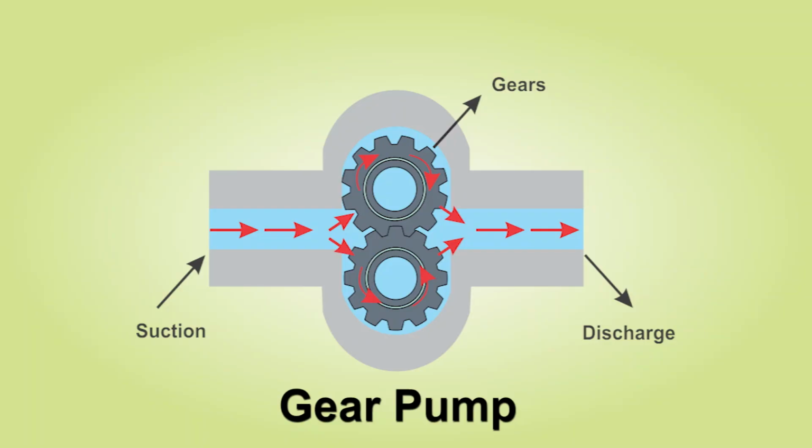Gear pump. Gear pump uses the action of rotating cogs or gears to transfer fluids. The rotating element develops a liquid seal with the pump casing and creates suction at the pump inlet. Fluid drawn into the pump is enclosed within the cavities of its rotating gears and transferred to the discharge. There are two basic designs of gear pump: external and internal.